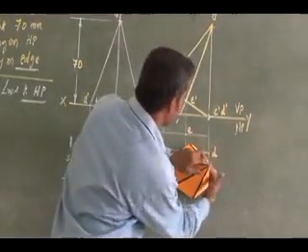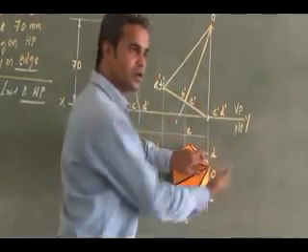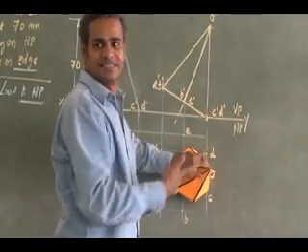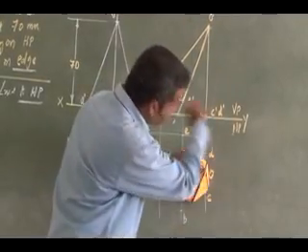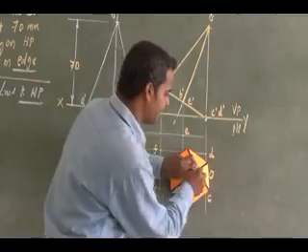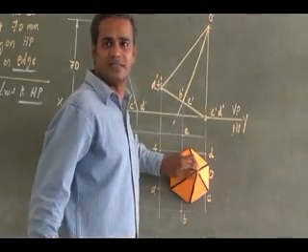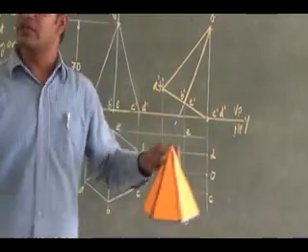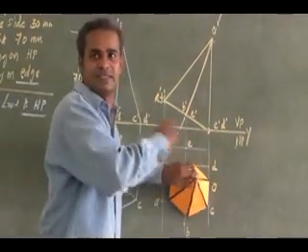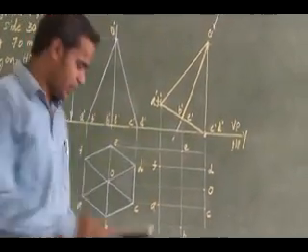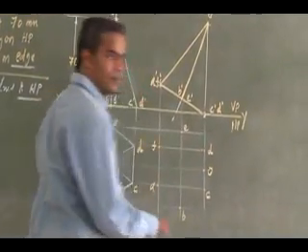This triangular slant face will coincide with one of the base edges, so I can see the base fully. If the apex is tilted outside the base, then the base will be partially visible. If the apex is tilted within the base, the base is fully visible. So now the base is fully visible.